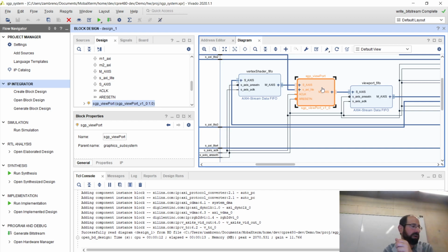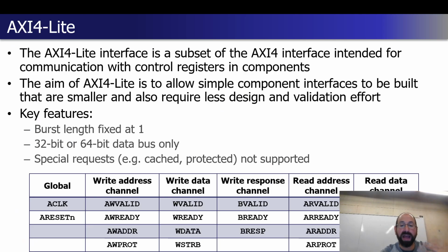Let me also register the actual input values that are coming in. Some assumption I have on paper to VHDL to test is not correct. The more debug information you add, the better off you're going to be in terms of finding that, versus where it can start to get a bit of a grind trying to find that information. But that's the value of AXI-Lite.